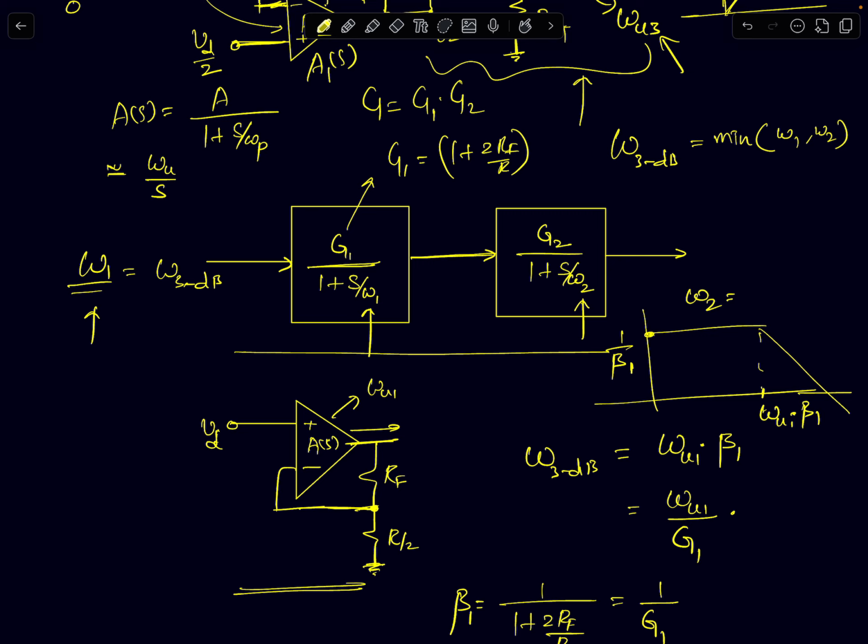In an actual design, depending on your op amp architecture, you may have to include that as well. But to simplify, we are only considering the first stage, assuming the load of the second stage doesn't impact its frequency response, which is true if you assume the op amp to be a voltage controlled voltage source model, meaning its output resistance is very low. If you use that approximation, you can ignore the resistance from the second stage.